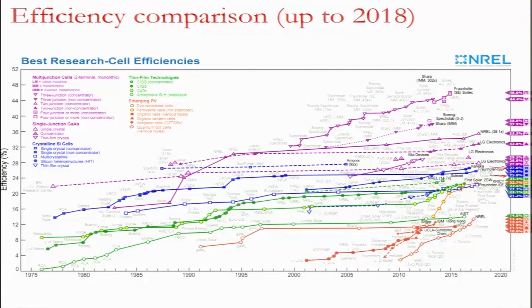And if you go to thin film technologies, the ones in the green, the CIGS has a number of about 23% right now, laboratory scale, in the concentrator mode. If you go to non-concentrator mode, the efficiency is about 22.6%, which is here. And cadmium telluride is about 22.1%. These are laboratory best efficiencies, but these are not the average efficiencies. So these are the world records in that sense. And then amorphous silicon lies low at 14%, and the work on amorphous silicon has almost stopped now.